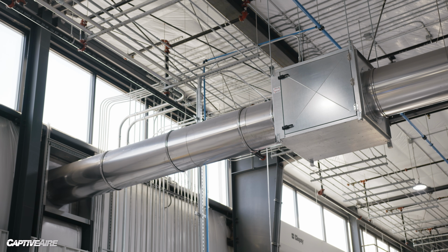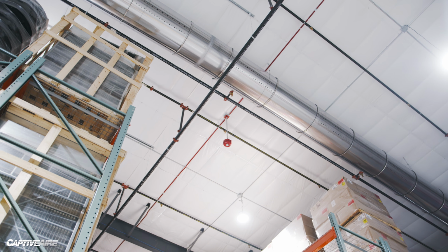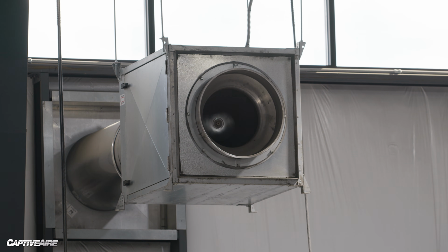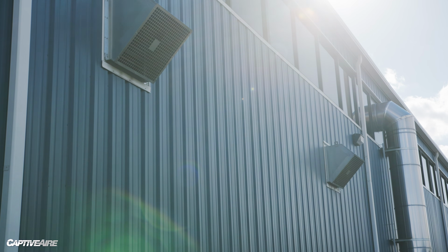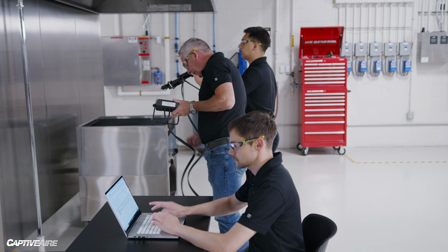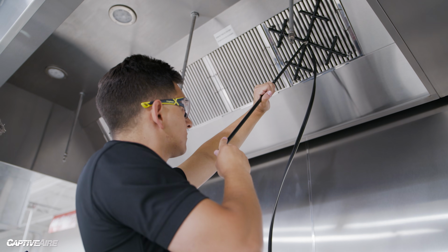And then as a general rule, you want to make ductwork as large and as straight as possible between the point where the air starts and the fan inlet or the fan discharge and where the air discharges. With system effect being such a key player, it's always good to give yourself some buffer when sizing up the fan. But in the end, how do we really know exactly how much air that fan is moving when installed in the space? We looked at test and balance in the previous video, which is great because it can account for any leaks in the system.